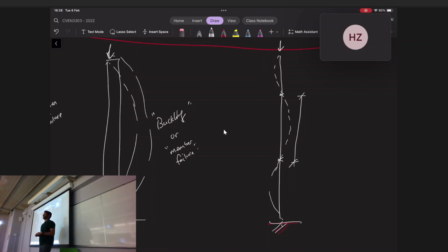Sometimes it can be any other bracing element, for example. If you've got a brace that's coming in to connect across the halfway mark along a column, then that's also a restraint. It can be a bunch of different things. As long as you look at something and realize that the thing connecting in is stopping the movement from left to right, that's a restraint.